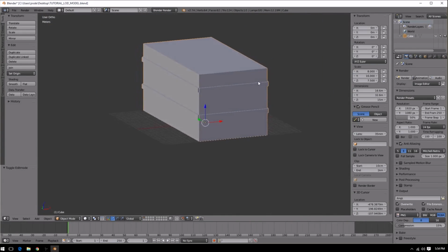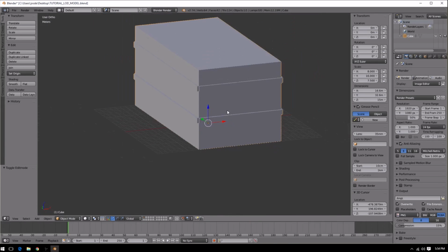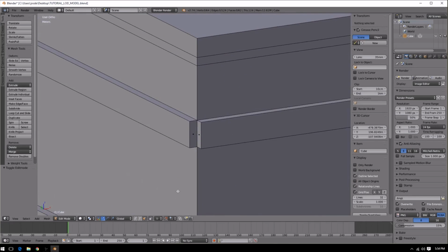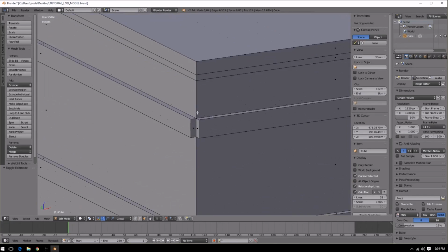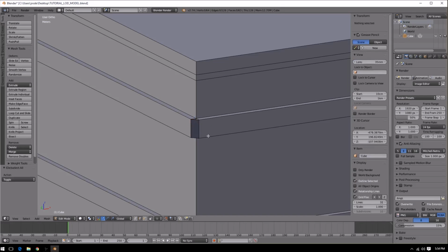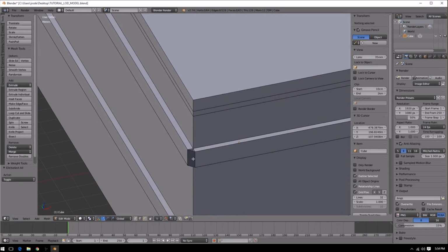There is a little bit of a difference, there is a little bit of shadowing, and there is some stuff going on here. One thing I don't like is these corners. So I'm going to fill these corners and create new geometry. One way to do this is by going down to your line or vertex select. At first I'm going to use the line select mode. Realize that you're going to have to use these tools constantly in different ways and different strategies. A cool thing with the line and vertex tool is that if you select two lines and click F, as in Frank, to fill, it will fill your two selections with geometry.